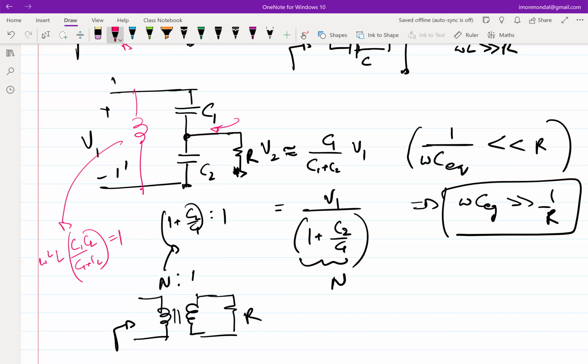Now you see that you just express your intent in English. You set up the network in such a way that it divides the voltage, and you resonate out the imaginary component, and you have a matching network for stepping up the equivalent resistance.